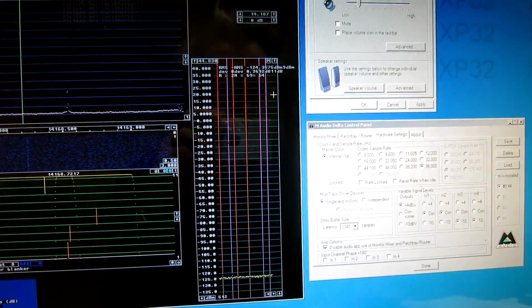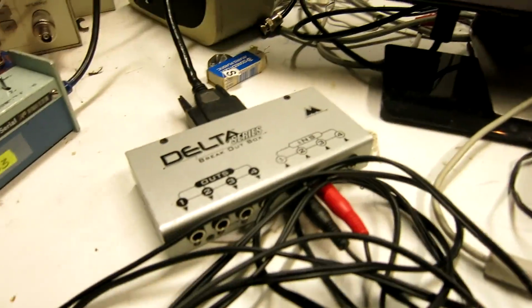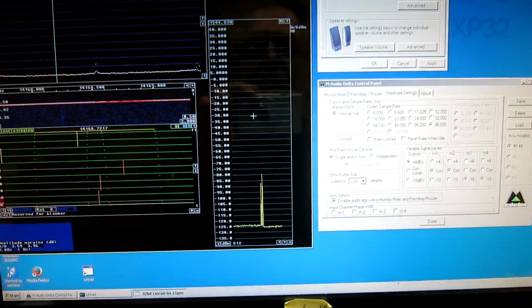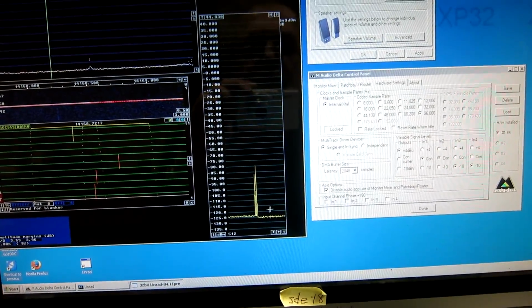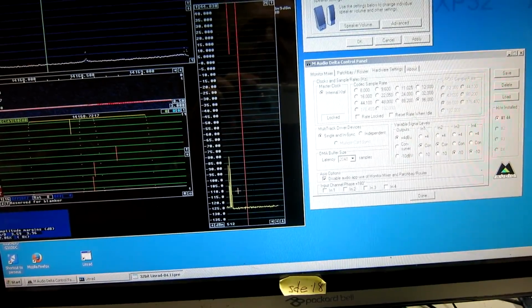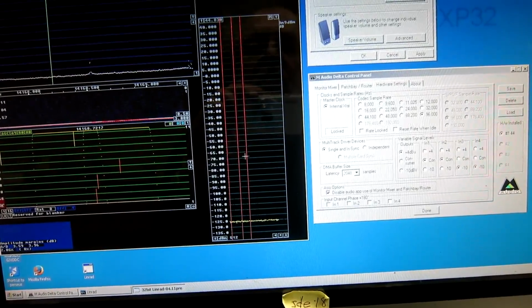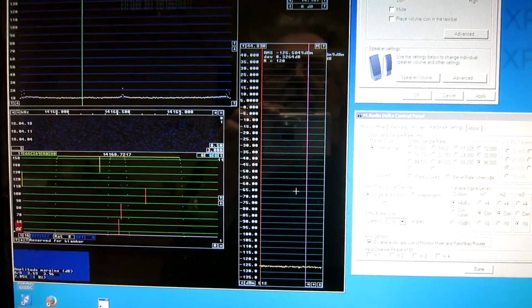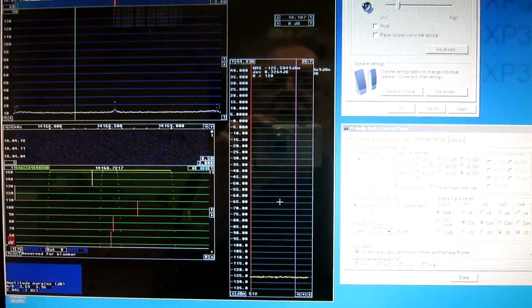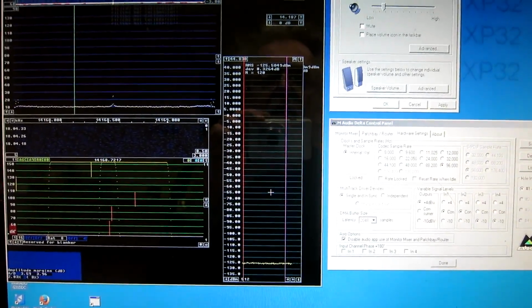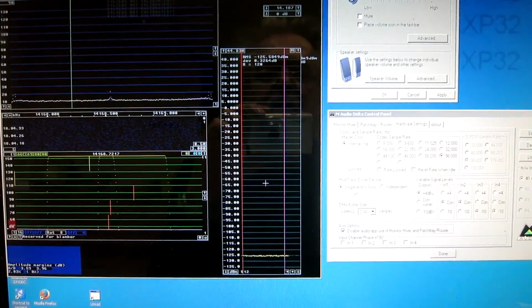Next thing to look at is what happens if we unplug the cable to the breakout box, like that, looking at the noise from the sound card only. Well, I can clear the graph like that, and you see the difference is small. But I can read it out, hopefully. No. Something is wrong, that this readout doesn't always work. Now the level is minus 125.5, well, 125.6. So most of the noise comes from the sound card, and a small fraction of the noise comes from the Softrock.